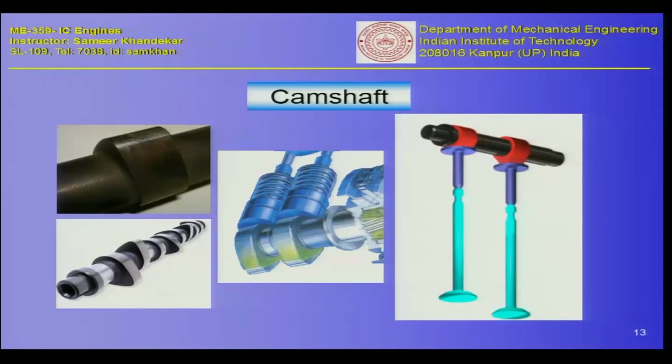on the PPT, it tells you how a camshaft operates, and this is essentially timed with the crankshaft through a timing gear, so that they open and close at the designated period of time and at a designated location, or with respect to the piston position or the stroke of the piston where the piston is at that moment of time. So this is a camshaft.